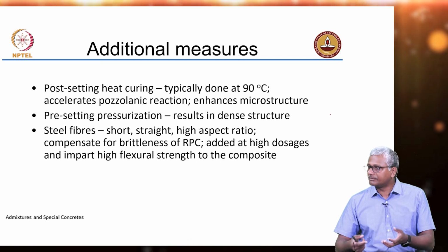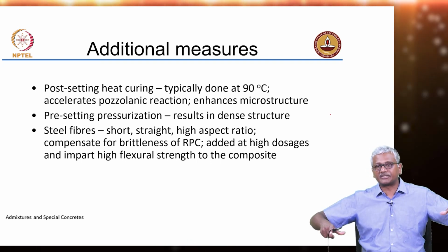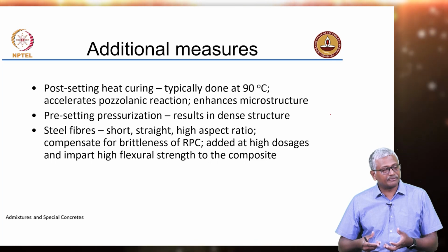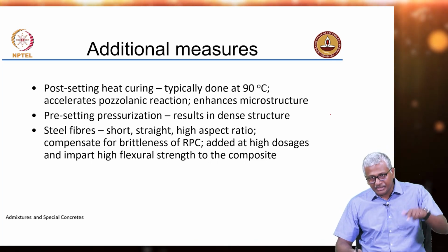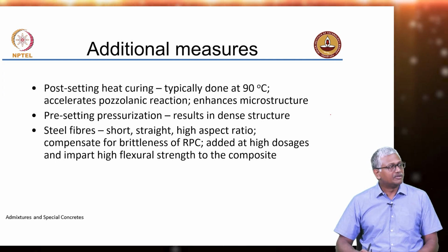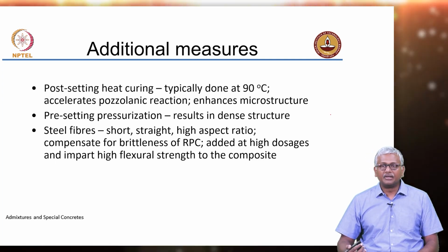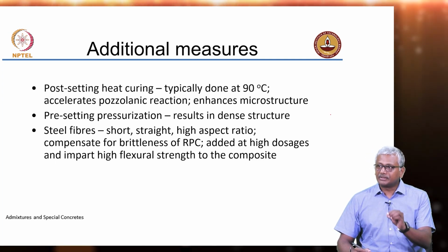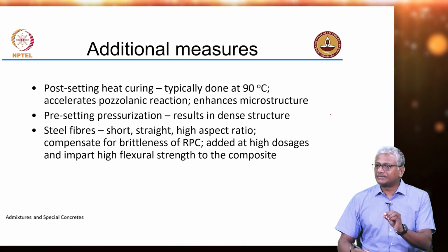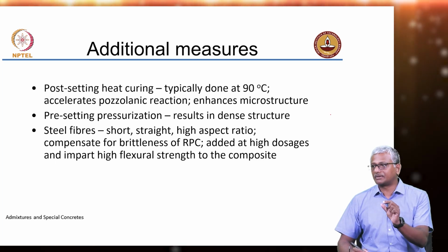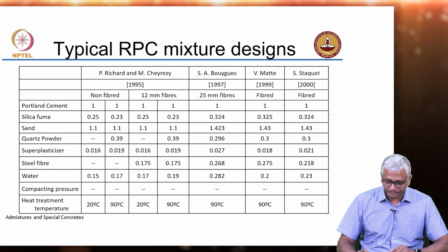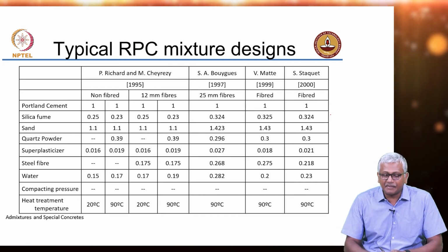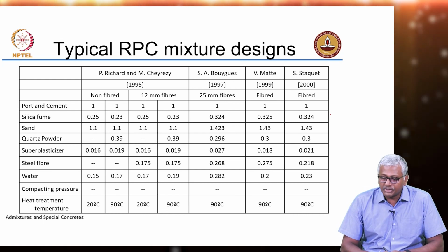If you do not have fibers, as soon as the crack appears, the concrete splits. But if you have fibers, it will sustain the deformation for a long period of time, and you will see major deflections of your beam before actual failure happens. Okay. So, here the fibers are actually small enough that they start bridging the micro cracks, and that enhances strength of the system also. So, these are some examples of mixed designs from literature.